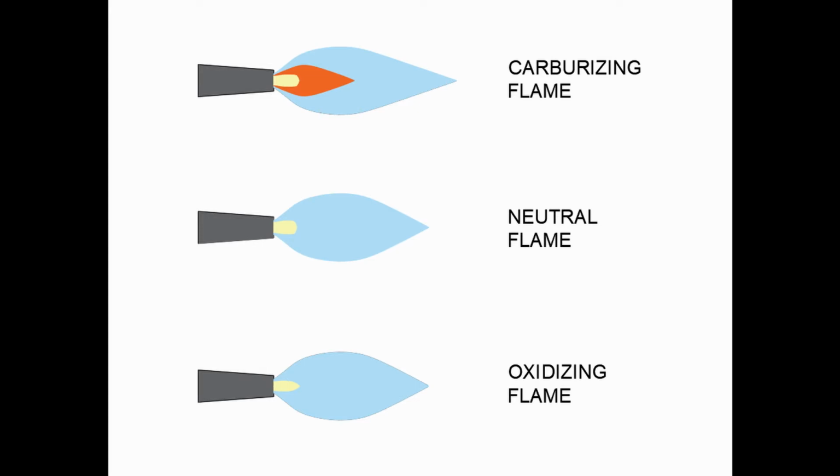Now let's talk about the oxidizing flame. By further reducing the acetylene flow, you will end up having an oxidizing flame. The difference between neutral and oxidizing flames is that both cones, especially the inner one, are sharp in their end and less wide in oxidizing flames. You will see these characteristics become more intense while you reduce the amount of acetylene. One distinct feature of an oxidizing flame is that it produces a noticeable hissing sound.